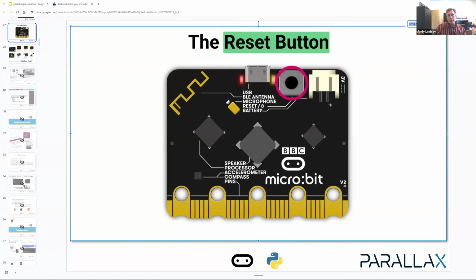Incidentally, just a side note, I had difficulty showing you the reset button on the microbit earlier. If you want to leave it connected to its USB cable and just restart a program that you've already loaded into the microbit, you can press and release this little button underneath the microbit. When you have the USB cable unplugged, you can also just turn power off and back on, and that'll restart the script that's loaded into it most recently from the beginning.